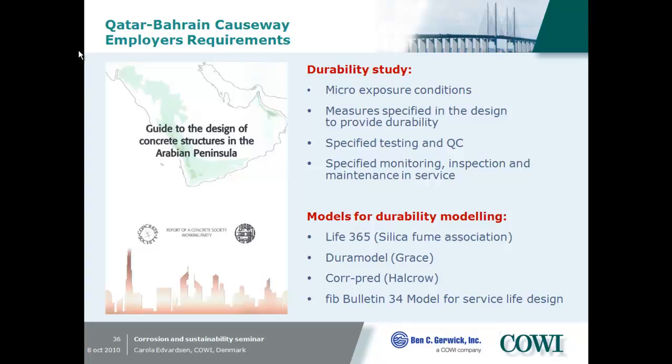The durability study should include a definition of the exposure conditions. We had to elaborate different durability strategies, starting with black steel and a very thick cover, over stainless steel, cathodic protection, prevention, and surface coating of concrete. And on top of it, we had to calculate the service life of these different strategies by using one of these models. It actually was standard in the employer's requirement, and we used the FIB-Duracrete model here,